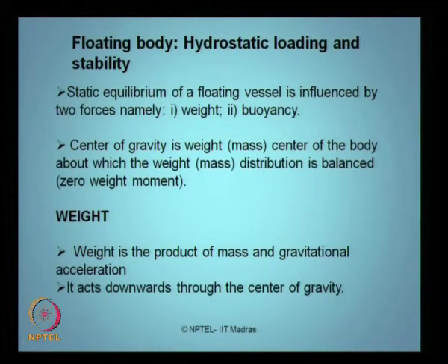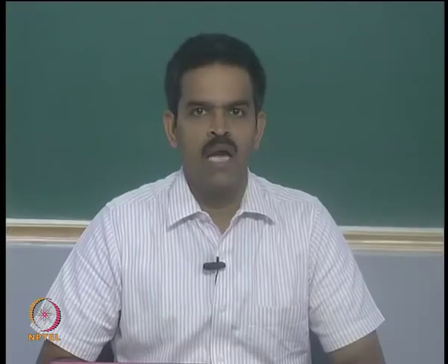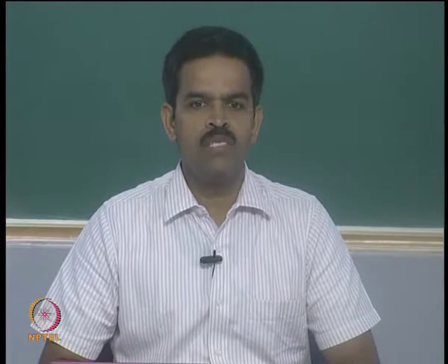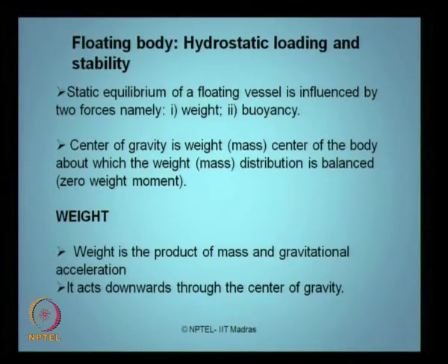After understanding how to compute the wind forces and wave forces, now let us see the significance of hydrostatic loading and stability of a floating body. The static equilibrium of a floating vessel is influenced by two forces, namely weight and buoyancy. The center of gravity is the weight or mass center of a body about which the weight distribution or mass distribution is balanced. We call this zero weight moment.